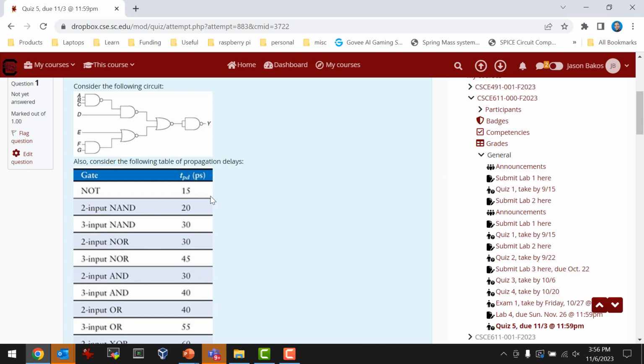So this is an easy circuit to analyze because you basically just have one path for each input to the output. You guys with me? If we had some branches in there, it might have been more complicated, but this is a pretty easy one. The problem is that all these gates have different delays. So you may need to calculate multiple possible delays,